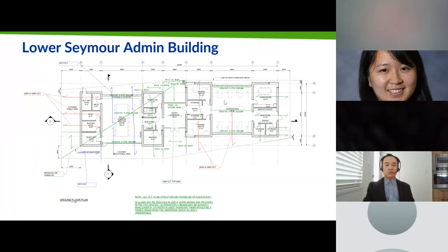So basically, the roof system is, again, CLT panels supported on a mixture of stud walls and beams. So obviously, at the ridges, we need ridge beams, and then elsewhere, we also need other beams. And we have a combination of glulam beams where they're exposed and steel beams where they're concealed or where we need to lower the depths of the beams or keep them to a minimum.